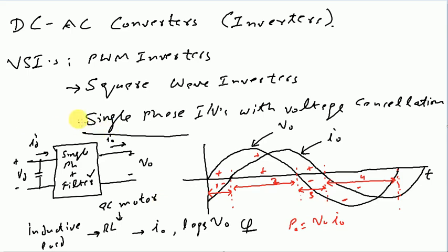Here in this case, our intention is to transfer the power from the DC side of the system to the AC side, and that is how this circuit will work in the inverter mode. So whenever we get a positive sign, that will result in an inverter mode of operation.